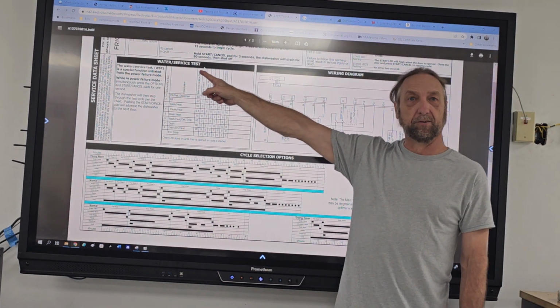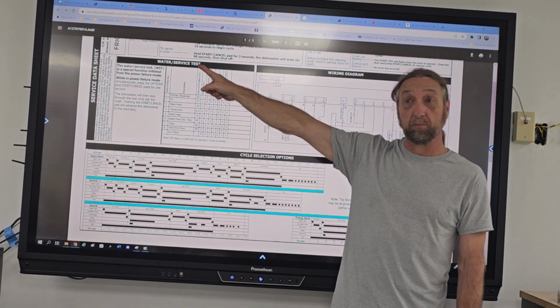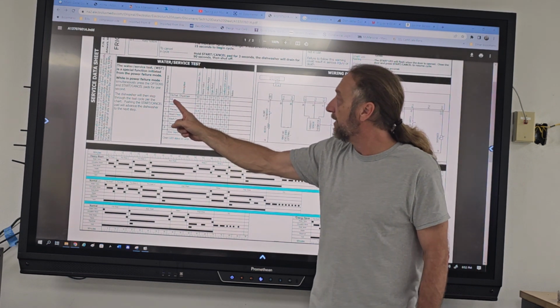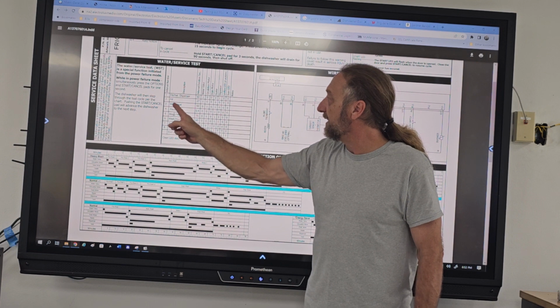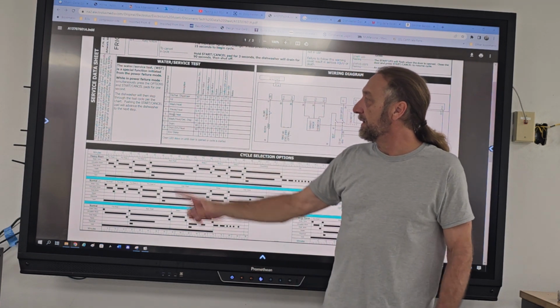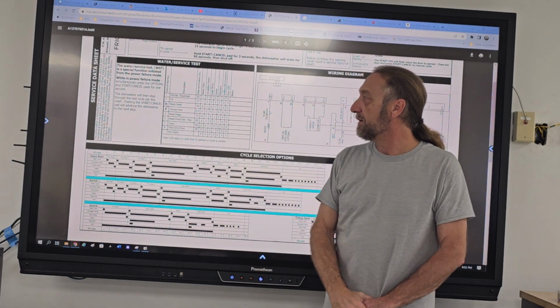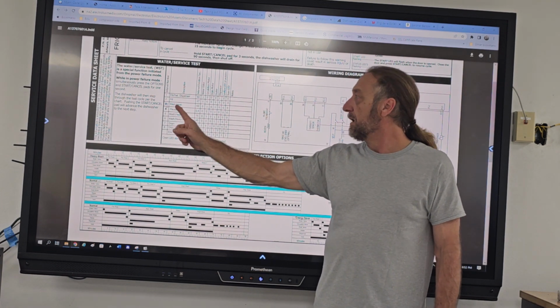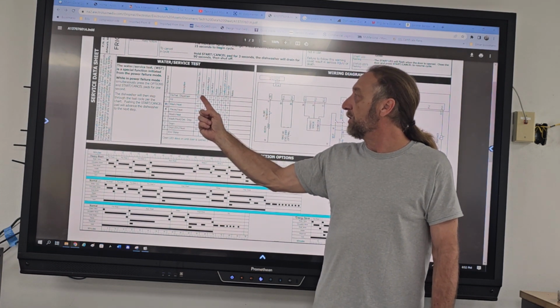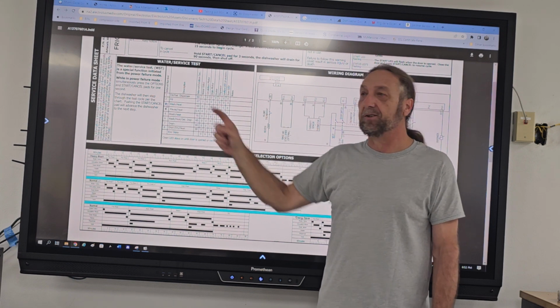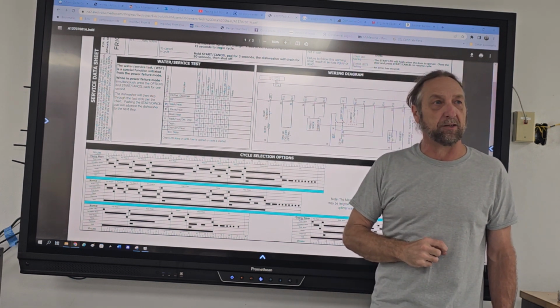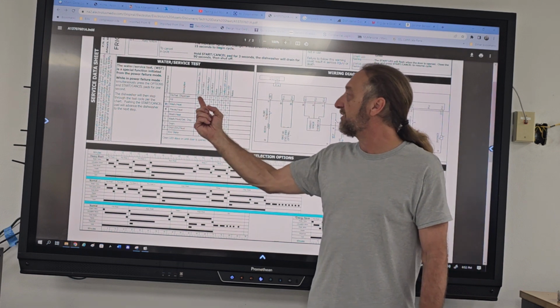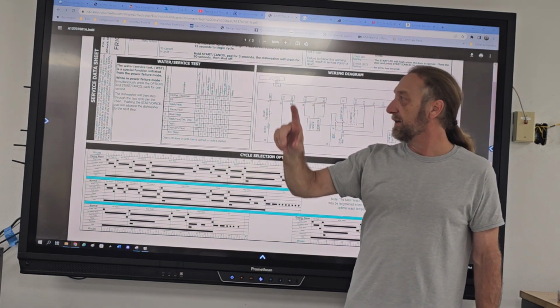Water service test. That's a diagnostic mode. Look here, where does it say that the heater comes on? In step number 3, right? It says it washes and the heater's on. So it tells you here, when you first turn it on, it's gonna fill and the detergent dispenser's gonna get energized. It's gonna last 60 seconds, 1 minute.